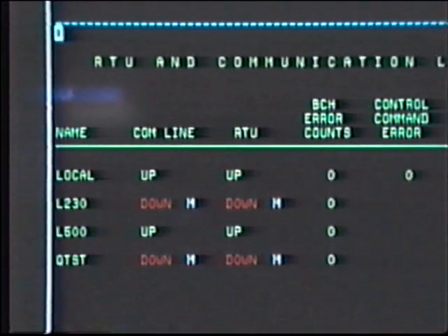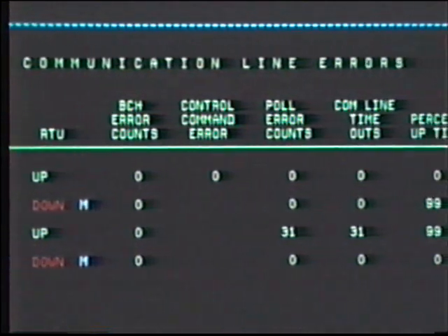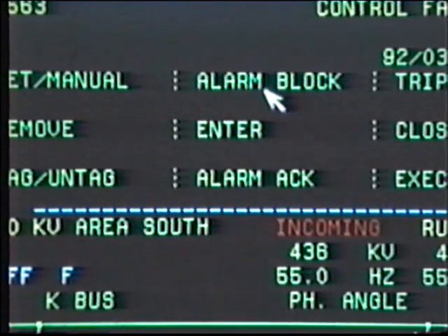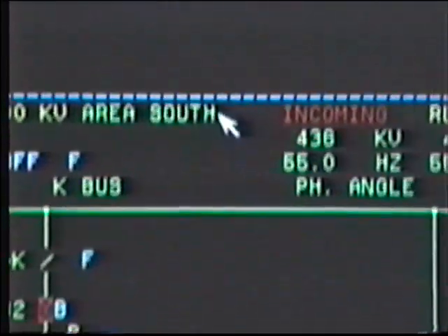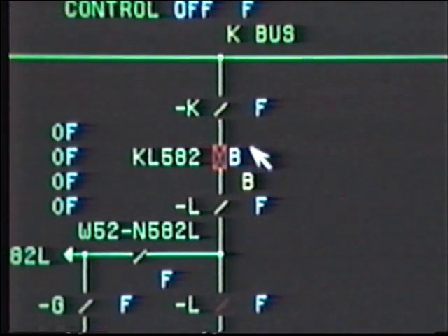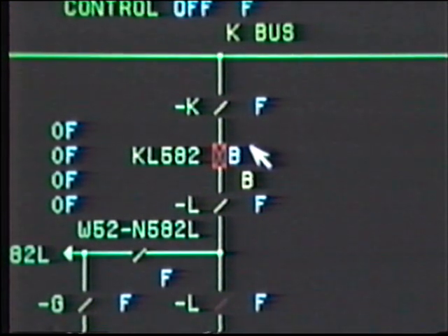Operation of the Scada system itself is continuously monitored and alarmed in case of any failure in the RTUs, the communication links, or any other components of the system. Transmission of an incorrect message will also be alarmed. The operator has the facility to disable alarms from any specific piece of equipment. For example, perhaps the equipment is undergoing test, with the result that many nuisance alarms may be activated.